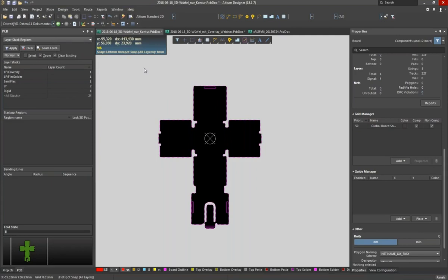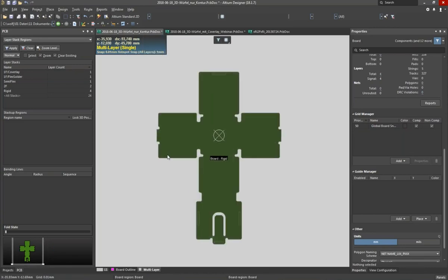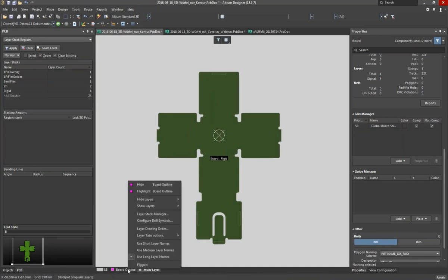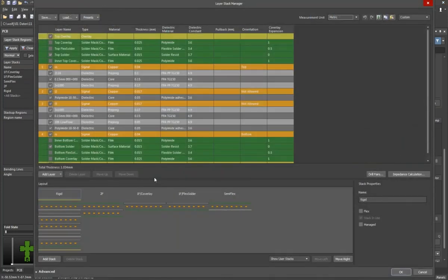Thank you, Andreas. And here you already see my Altium screen. And what I did is I prepared the board outline for this new digital sample. So normally, when you look into your design and into your conception phase, at some point your mechanical department or your mechanical structure is done. And you either import your board shape into Altium by using, for example, a DXF file, or you create your board shape in Altium by using the mechanical layers.